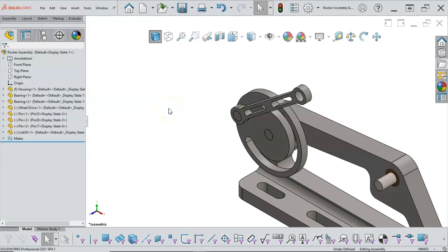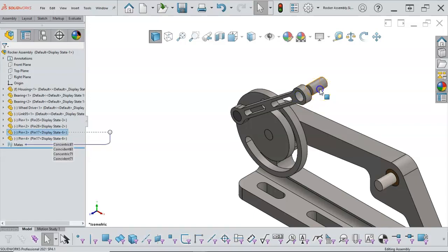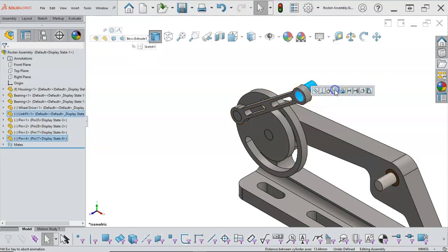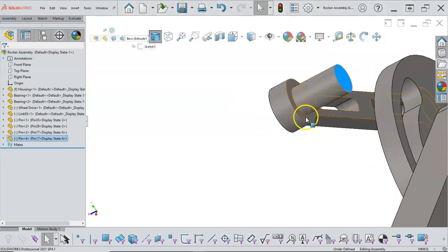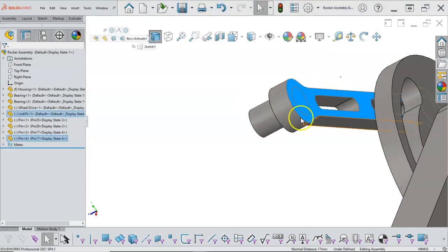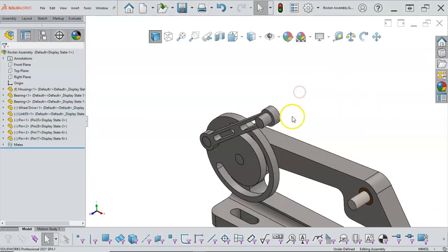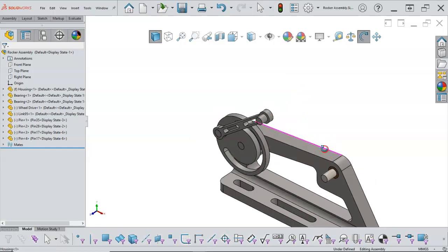All right, and then assuming that that's going to be another 17mm pin, looks like there's a little bit of a gap. I'll go ahead and reorder. And I'm going to go ahead and thumb on the control. Not picking that up. All right, well. Concentric. I'm not worried about lock rotation on this, since that doesn't have a bearing in it and there's no retaining.